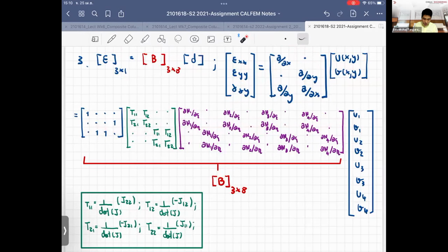When we expand the forms here, of course, this one is just about how you can match them to the derivative of X and Y and so on. This is in terms of the strain in X, strain in Y, and the shear strain. The matrix here is the inverse of the Jacobian matrix. So that's why we take it as a tau, right? Which is the Greek symbol.